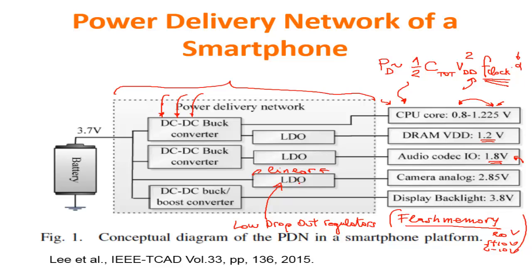You have seen an example of a linear DC-DC converter with feedback during the first course in electronics, and the principle of operation is essentially the same. The most important characteristic of LDOs is that they can also work with a very low difference between the input voltage and the output voltage. But apart from that particular aspect, in their essence they are linear voltage regulators.